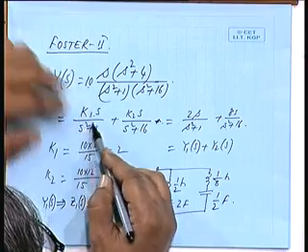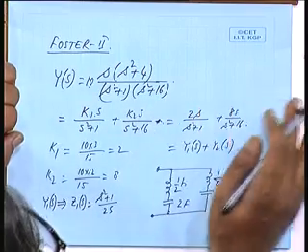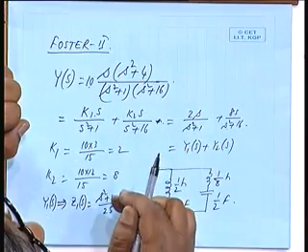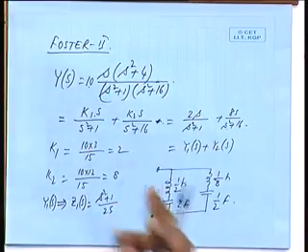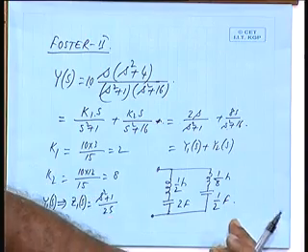If it is a very big Z(s) function, we can realize terms like, say, K1 s by (s squared plus 1), and the rest of it we do not realize. So subtract it from here, and whatever is the balance you switch over to Foster 2. Suppose you have started off with Foster 1, realize only one pole by Foster 1, and the rest of it you again combine and then realize by Foster 2. That is also possible; any combination is possible.